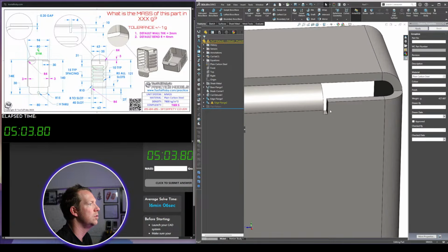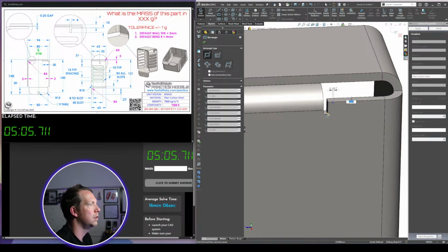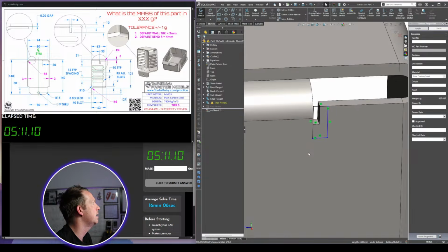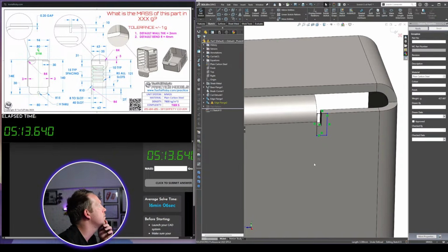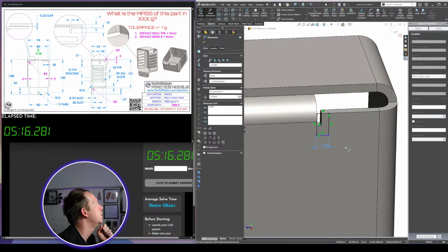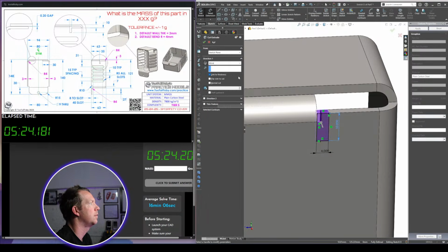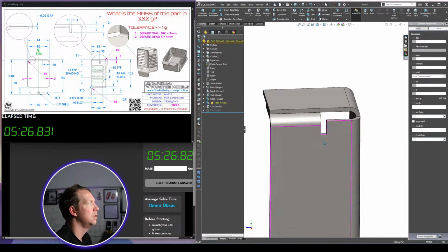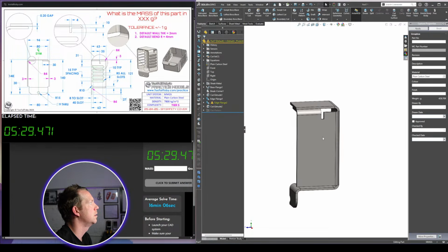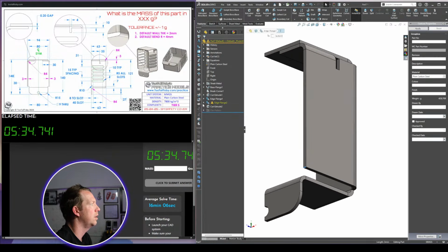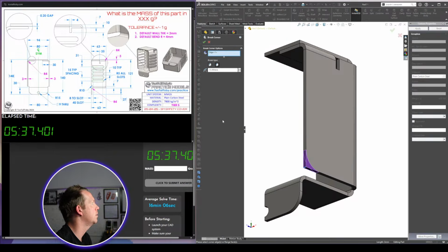And now I can just tweak this. What I need to do is just get the right size for this cutout, which is 4 and 10 from that edge. Okay, link to thickness. Alright, so that's done. The bend's looking alright. We have a break corner here, which could just be a fillet again, but we can put it in. It's 10.